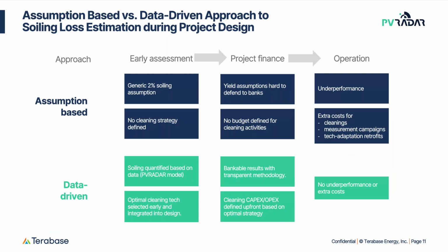The standard approach, and the one that we see most, is the assumption-based approach, where during early design, a development team makes certain assumptions about soiling that are maybe based on experience, or maybe some Excel spreadsheets summarizing some of the data they have been able to gather. But really, they are assumptions about the soiling, and most famously, the 2% that PVsyst once introduced. This 2% usually comes with the assumption that no cleaning is necessary, or at least no cleaning strategy is defined.